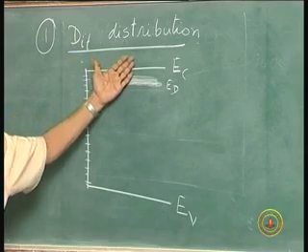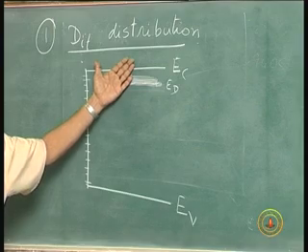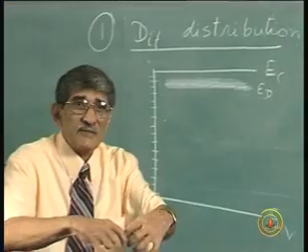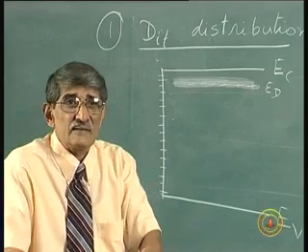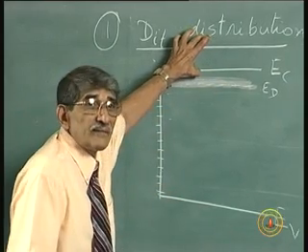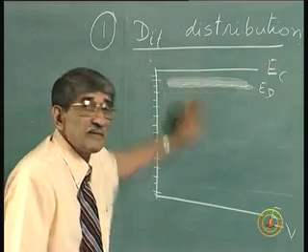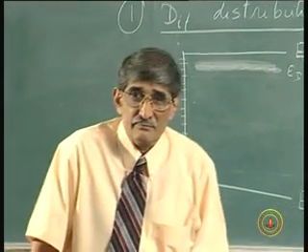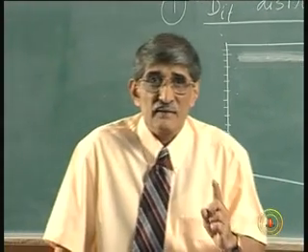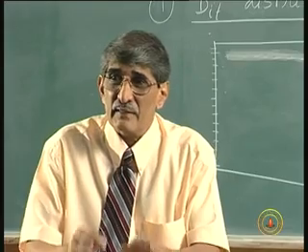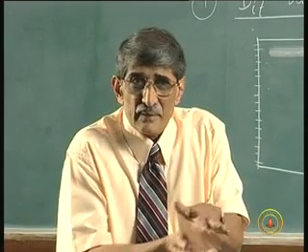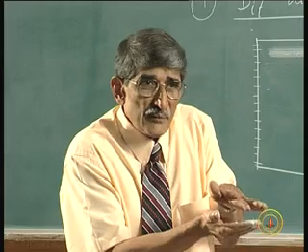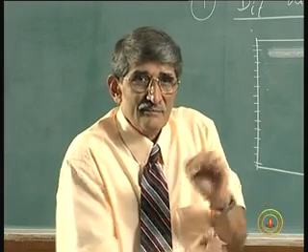The conduction band is formed because there are silicon atoms which are nearby. The electrons in the outermost shell interact with each other, and multiple levels you get. Same thing happens with impurity when the impurity concentration is high. So, the same type of impurity can give an energy band, split over. As you keep on increasing doping, the impurity band becomes wider and wider.